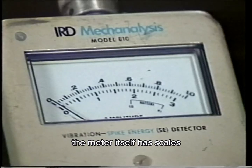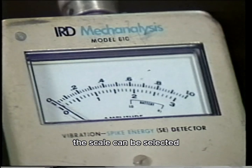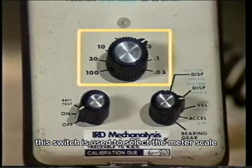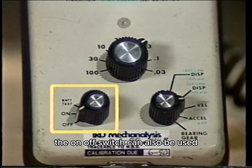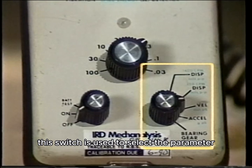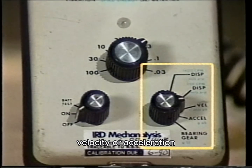The meter itself has scales, each of which has a different range. The scale can be selected according to the amount of vibration being monitored. This switch is used to select the meter scale. There's also an on-off switch. The on-off switch can also be used when testing the batteries. This switch is used to select the parameter to be monitored, either displacement, velocity, or acceleration.